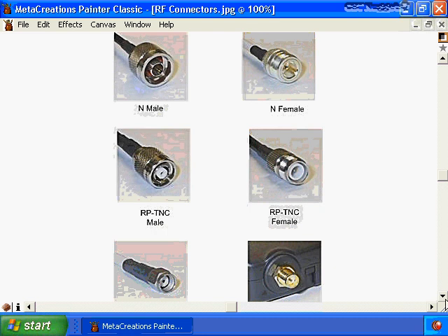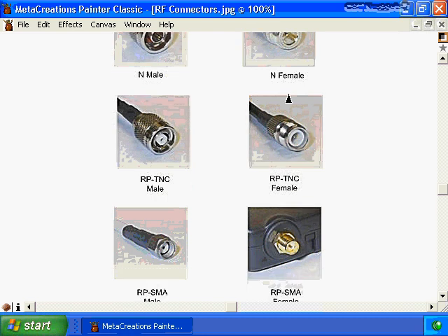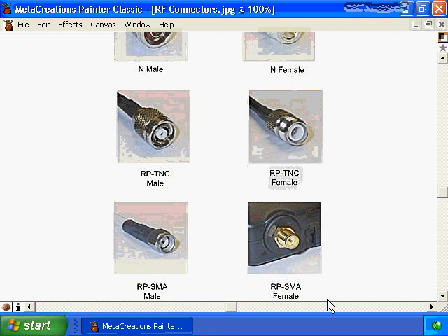So these are, again, typical types of connectors, but again, I hesitate to say standard types of connectors. When you see a connector that does not have RP in the front of it, that is an industry standard connector. When you see a connector that does have RP in front of it, that is a non-standard or proprietary connector. And similar to purchasing the other wireless LAN accessories that we talked about, there's a specification checklist that you should go through when you're purchasing connectors for your wireless LAN.